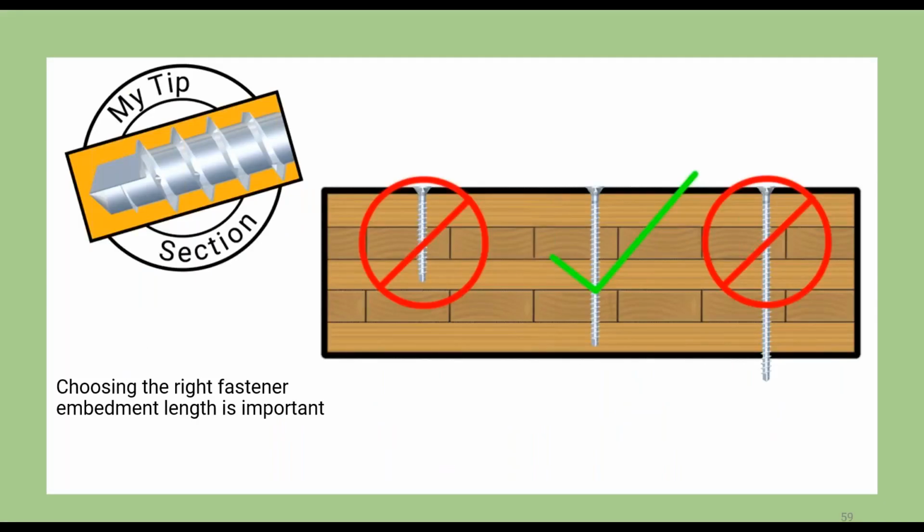You might be thinking why we're choosing a capacity for the anchors that's much higher than we need. The most important thing when you're choosing the right fastener is a good rule of thumb: the fastener should engage the most amount of plies possible. So the length of the fasteners and the thickness of your panel are very important. This way, the risk of delamination is reduced and the stresses are propagated properly. And we know that fully threaded screws are a good choice for lifting.